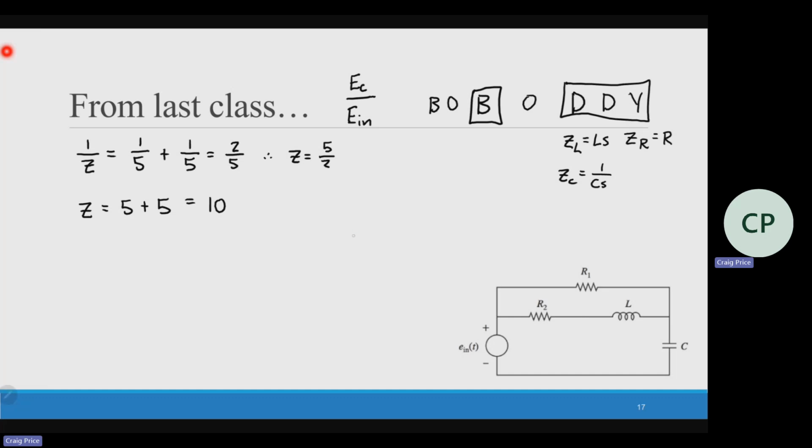I've had some people that add stuff up, they take it to the -1, but they don't really know what to do with it there. So just trying to do each part together. Like, for example, in this problem, I would do these two first. They're in series. So I would do that one first, just all by itself, just to find one Z equivalent. And then you can think about the next step, which is combining all of them. Well, if you did it all at once, it's possible to get it right, and it's also more possible to make a mistake.